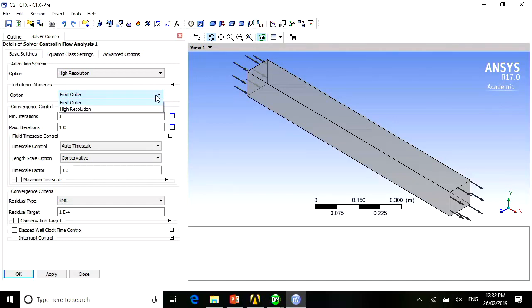Another thing you look at here is that the maximum number of iterations is 100. You can change this, okay? By default, it's set to 100. Some solutions take 1,000. Some solutions even take 2,000. It really depends. For this problem, I know 100 is enough because it's a very simple problem. You get convergence before that. The reason I say it's appropriate is because it all depends on what criteria you set here, 1e minus 4.